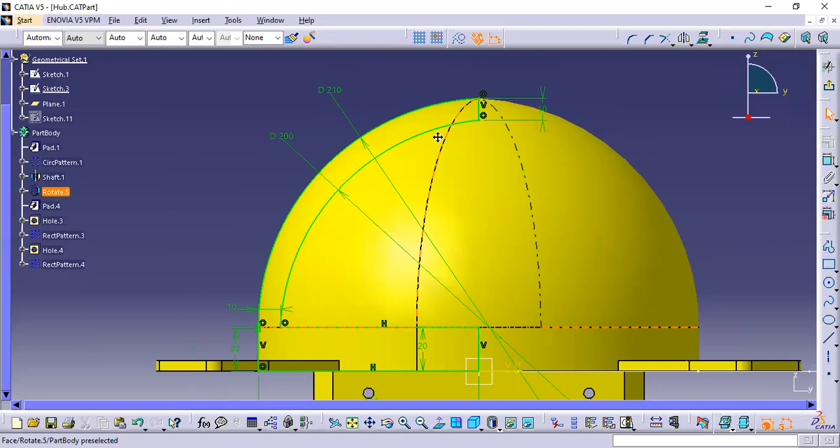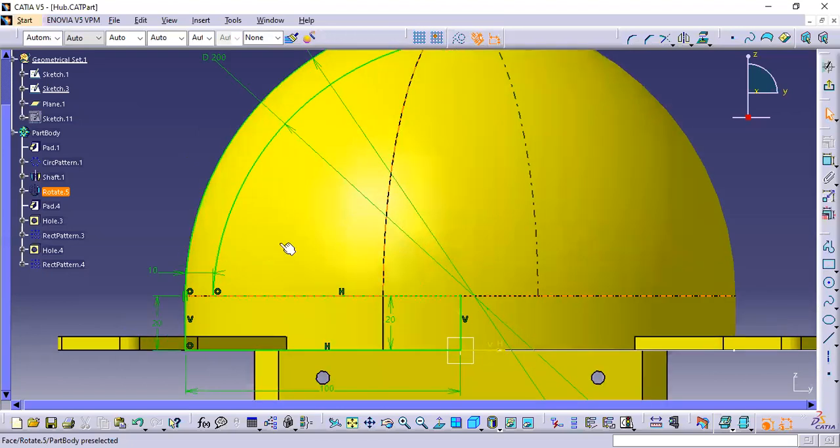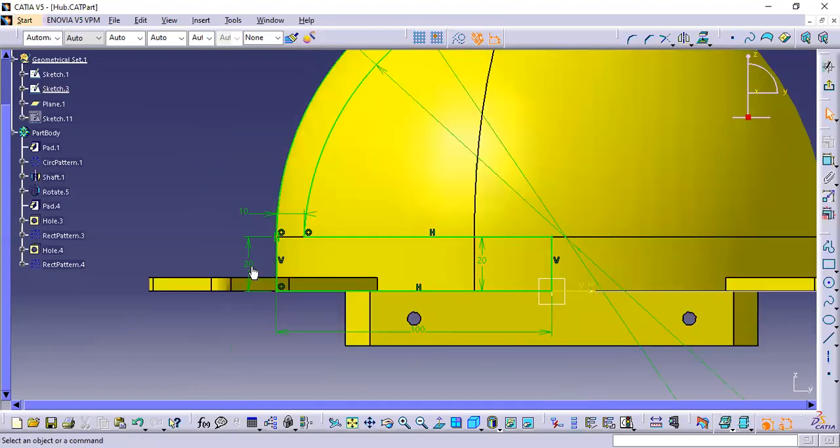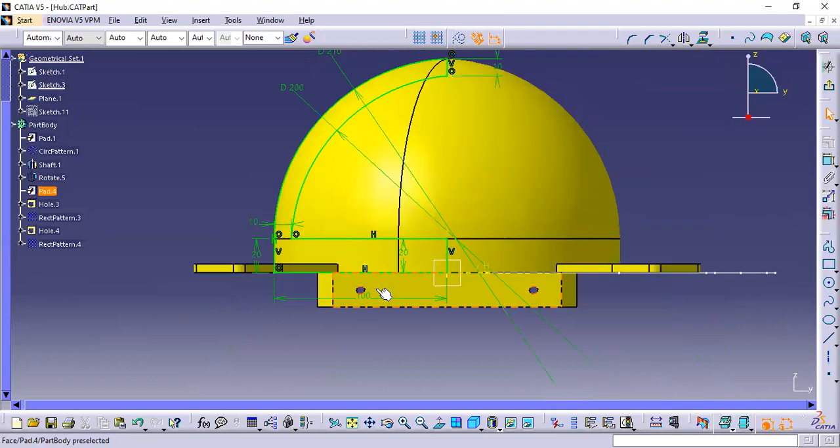This is how we ensure that the interior will be empty and not a solid body inside. And here the base is 2 cm, which is 20 mm, from the base, so it will add additional stiffness or additional material.